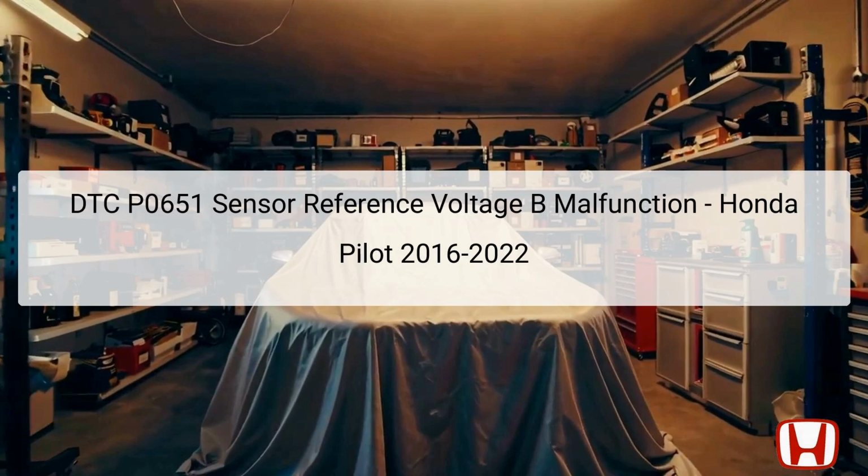The DTC, or Diagnostic Trouble Code P0651, refers to a sensor reference voltage B malfunction in the Honda Pilot models from 2016 to 2022. This error usually indicates an issue with the voltage reference provided to various sensors, specifically the second voltage reference line in the powertrain control module, PCM.